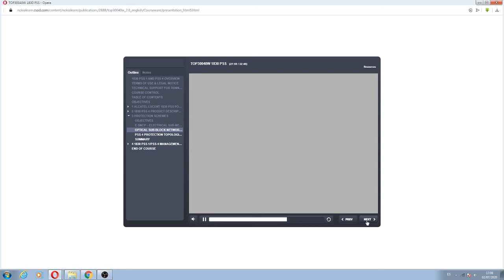So the major advantage of using the Y cable is that you can specify a level of signal degrade at the OT as a protection threshold. Protection switching can be set as revertive or non-revertive. The backplane is used to communicate with each pack to determine the pack that is active and is in protection mode.